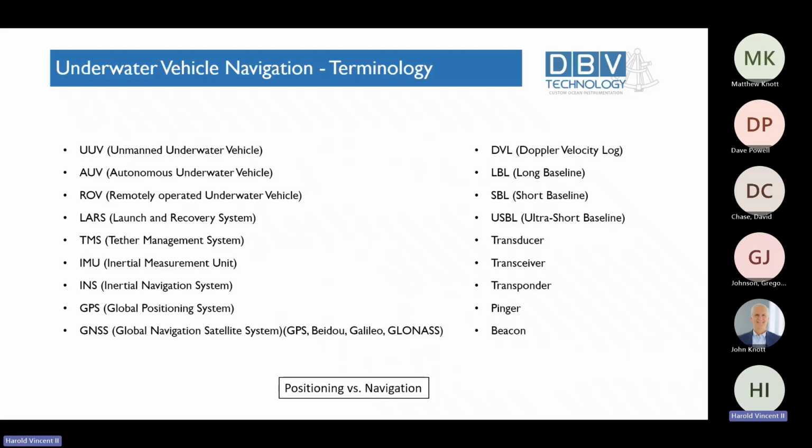Number two, a transceiver is usually initiating the downlink, or this transmission of the acoustic signal, waiting for a reply or receiving an acoustic signal, and then doing some processing on that to determine something like a position of the underwater vehicle, to allow that to be used in conjunction with the inertial navigation system.